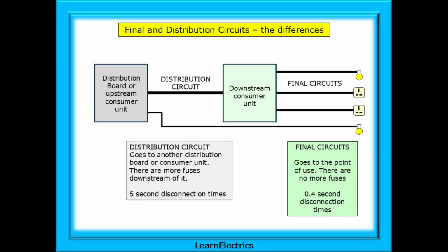As a reminder, what are the differences between a final circuit and a distribution circuit? Shown here is a distribution board that is feeding a downstream consumer unit. The cable between the distribution board and the consumer unit is a distribution circuit.